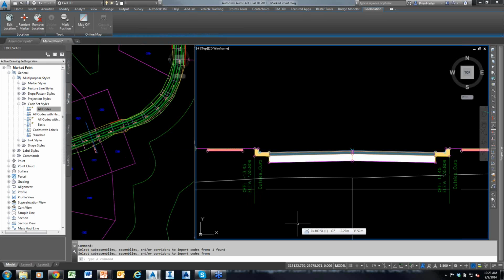You can also use marked points to create specific feature lines. If you're using overhang corrections and you're trying to create that datum surface, a lot of times those datum surfaces need feature lines to help flesh out the surface, but the problem is we don't have the codes to create those feature lines. Well, go put marked points called datum feature lines anywhere you need those, and then add that feature line to your surface, and it'll help things out tremendously.